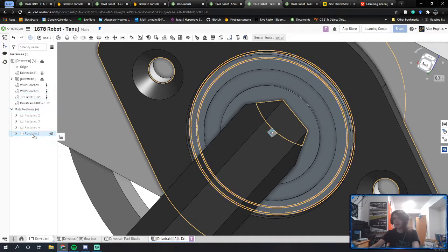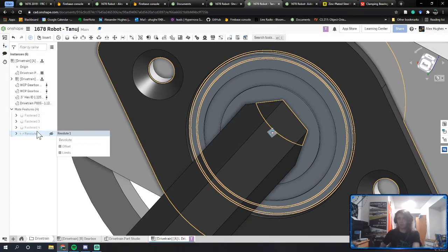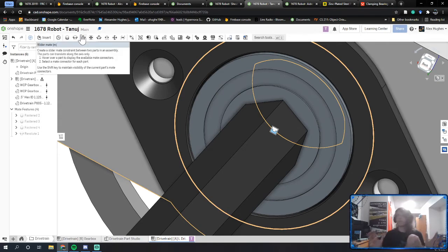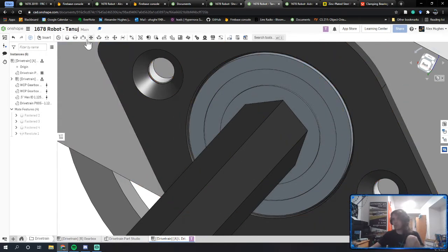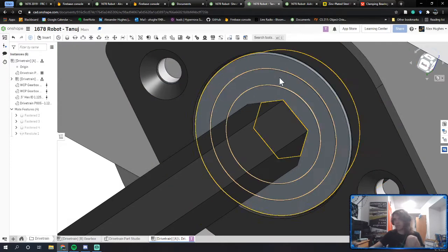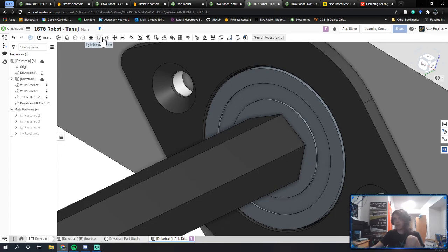No, you can't apply multiple fasten mates because a fasten is like a one time. It will fully constrain your mate. Every other mate allows some other axis that you can rotate on, and so you could do multiple of those mates. So you could have a revolute mate and a slider mate, or a planar mate and a pin slot mate, but you can never have two fasten mates. You could also never do a cylindrical mate and a fasten mate, or a slider mate and a fasten mate.